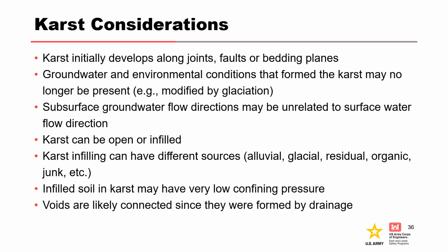Karst can be open or infilled. Karst infilling can have different sources, such as alluvial, glacial, residual, organic, or junk. Infilled soil in karst may have very low confining pressures, and the voids in karst are likely interconnected since they were formed by drainage.